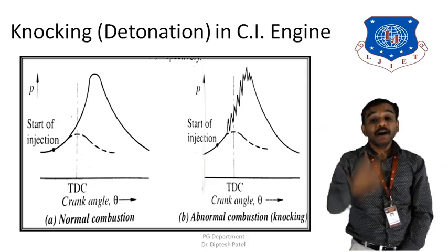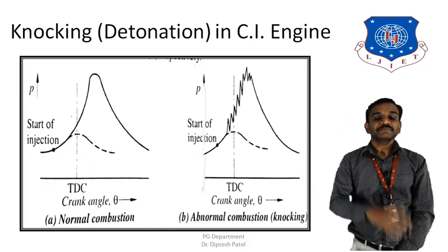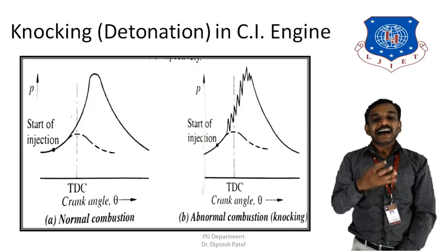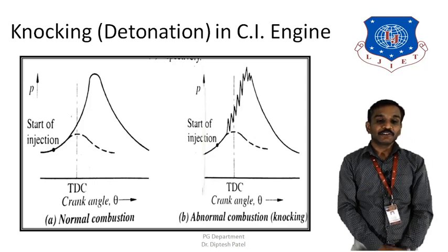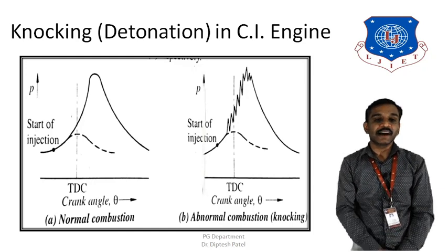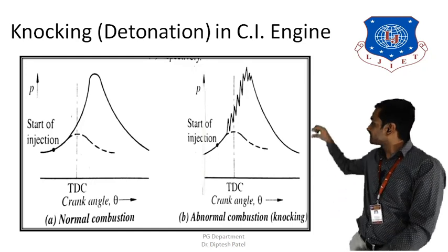But in abnormal conditions, because of the delay period, a large amount of fuel gets accumulated, and as the quantity of this fuel is higher, uncontrolled combustion takes place.